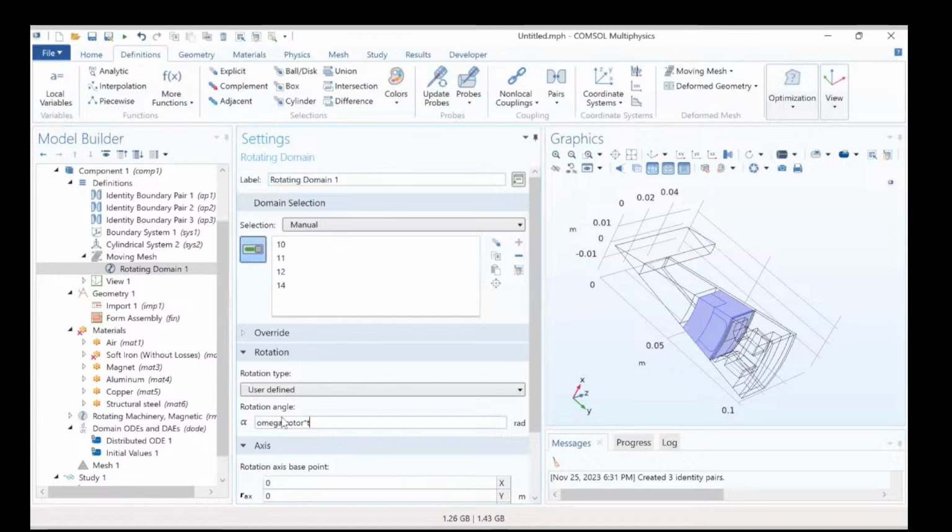So we're done selecting the boundaries. I think I missed one. It should be like this. Go to physics and fix boundary, and should have under the pairs the sector symmetry. And we click add. We select identity boundary pair. Use case add.